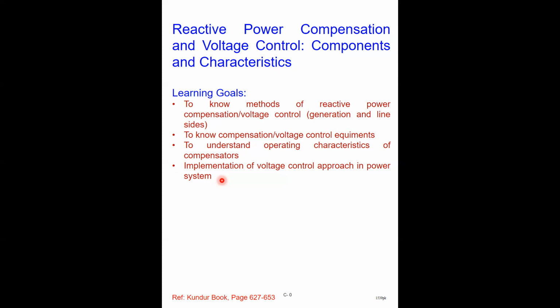There is a policy that it has to be achieved through the renewable generation components, let's say the smart inverters, or even wind farms or wind systems, they should also in some way contribute towards the reactive power compensation, and thereby the voltage profile improvement in the transmission network or the distribution network. But here in our discussion, we will only focus on reactive power compensation or the voltage control at the transmission network only, right?